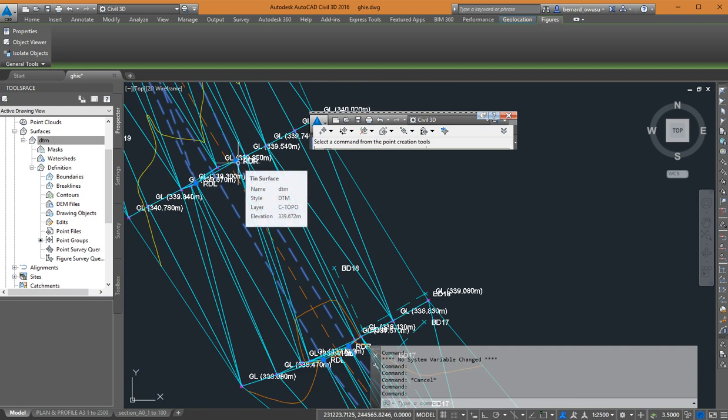You understand? For example, if you have a road on an embankment, it means that in the triangulation it has connected a point from the ground to one road edge. But we don't want that to happen, because then you will not have the road appearing as it ought to. So we want the triangulation for the road to be confined to the road. You understand? We don't want a point from a road to connect to a ground level or something. When it happens like that, you will not have a perfect existing road profile.